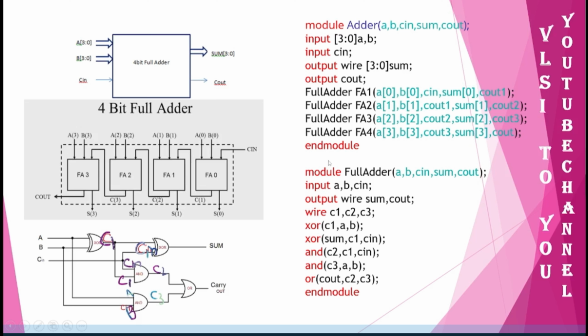Now what I am doing, after making the copies, I am going to write the basic full adder logic. So I'm just making one full adder and I'm copying 4 instantiations of that. So I need to write the basic full adder code. If you see here, A, B, C in, sum, C out. Okay, so I am writing this basic full adder.